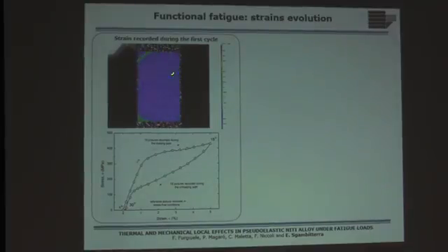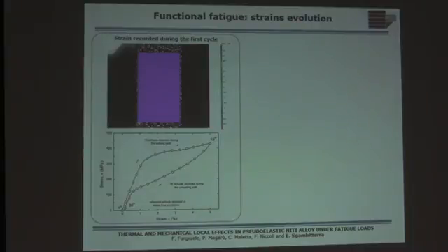So when you remove the load, of course, the martensitic bands tend to vanish, but at the first cycle they tend to vanish. But if you continue to work, of course, you have a ratcheting effect, an accumulation of the residual strain. It means accumulation of martensite strain.